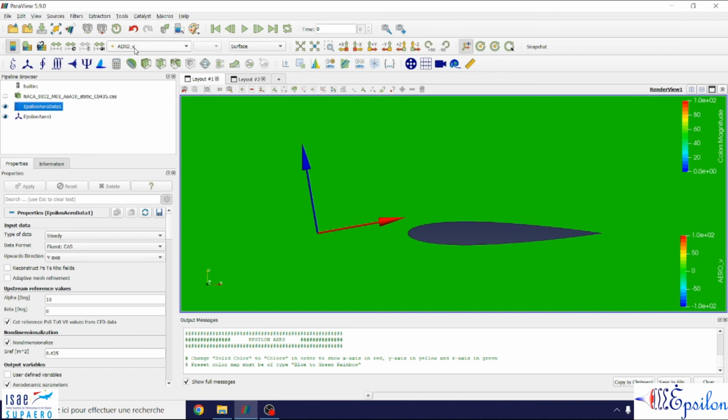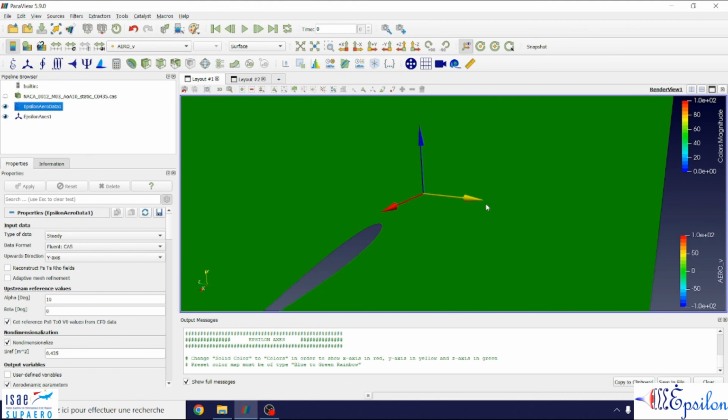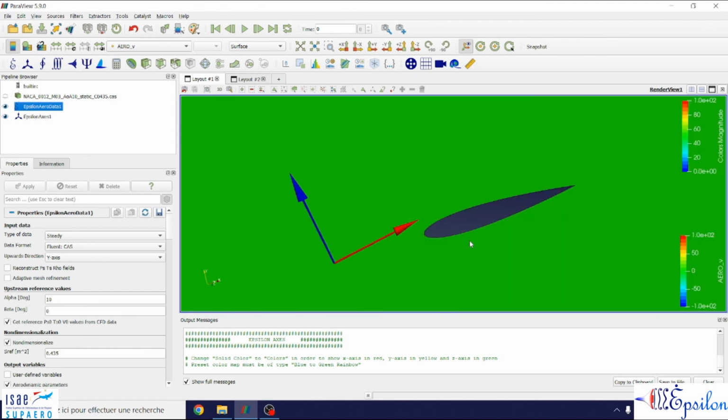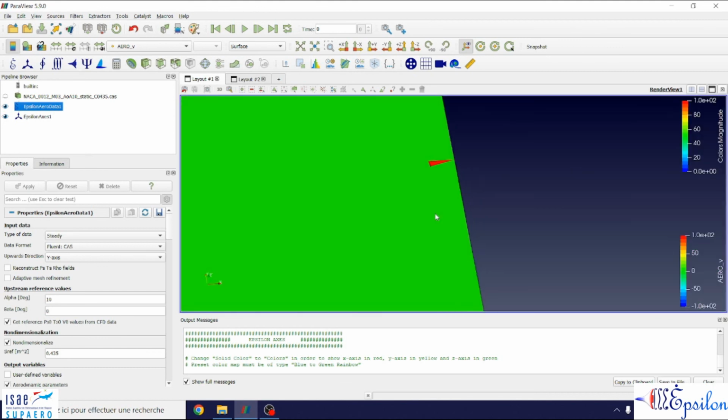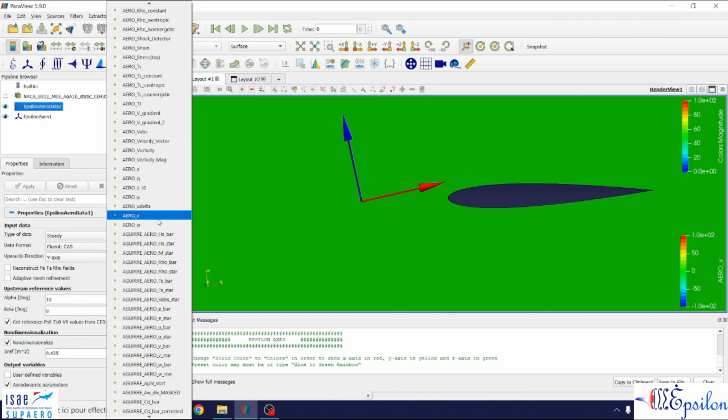Again, this is V. That means this is velocity component aligned with this yellow arrow that is normal to the plane, and it is coherent with this reference system. But if you say V velocity component in the mesh, it should be the vertical because it's the Y component. So it would be senseless to analyze the U, V, W velocity components in this reference system.